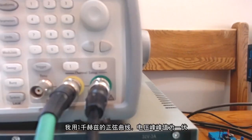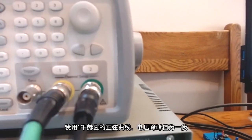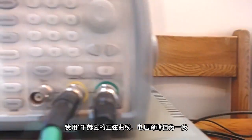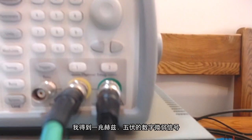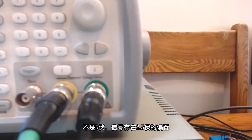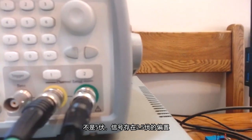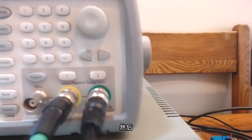And on channel A, I've got a sinusoid of 1 kilohertz, 1 volt peak to peak. And on the second channel, let me just read off what I've got. I've got a 1 megahertz, 5 volt digital logic signal, 0 to 5 volts, and it's got an offset of 2.5 volts, which is really useful to demonstrate certain things to you.